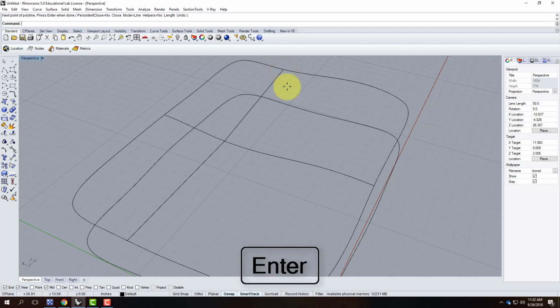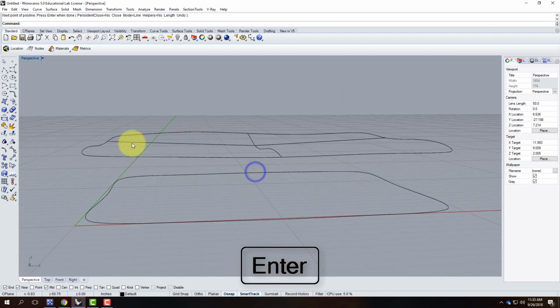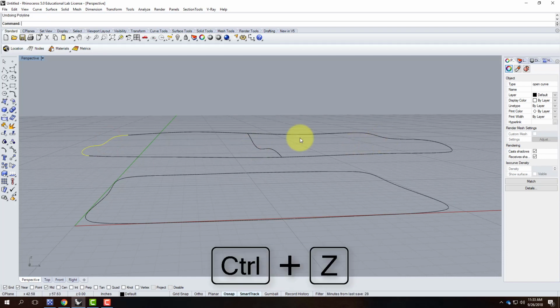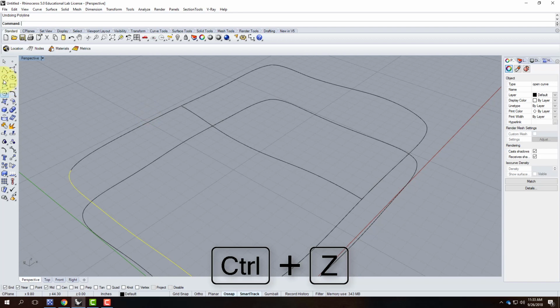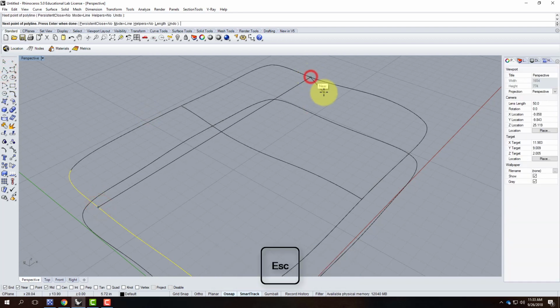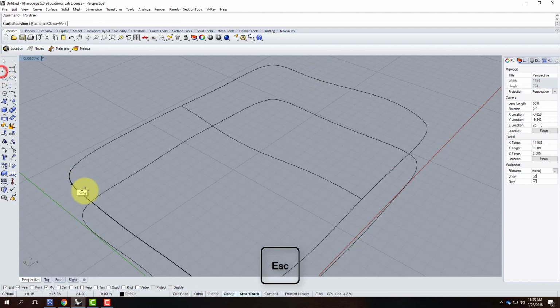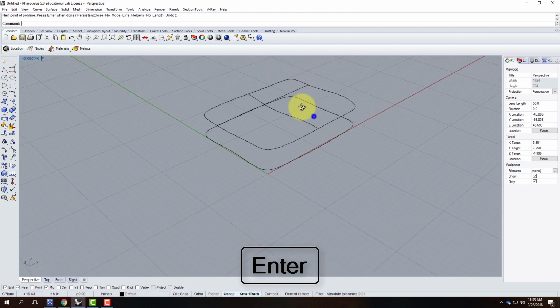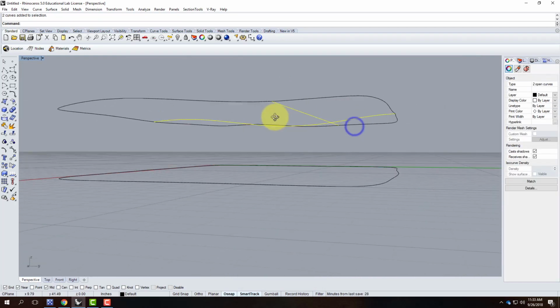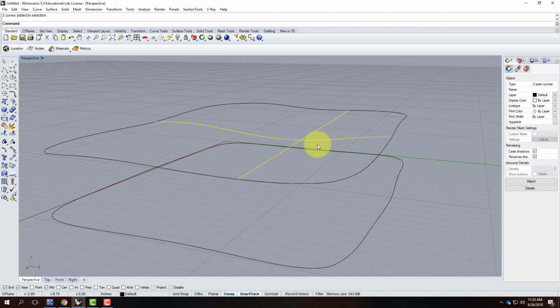So there's a few important things to keep in mind. I took this line, and I snapped to this line, I snapped to my middle, and I snapped to there. If I drew this straight across instead, and I said there and there, oops, sorry, and I tried to do a curve network, we've got a problem, because these 2 curves go across each other but don't intersect.